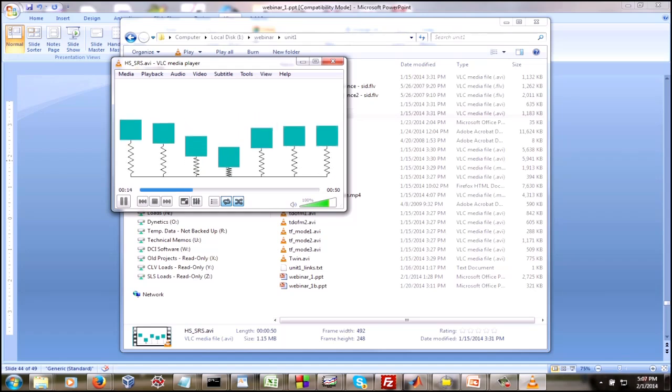Well, there's some other concerns we might have too, and if you deal with avionics components on launch vehicles, you'll come across things like C-band transponders and telemetry transponders or telemetry transmitters, and these tend to output a lot of heat energy, and that heat energy needs to be dissipated. So maybe that avionics component is mounted on a metallic bulkhead which serves as a heat sink, and it needs to be hard mounted for maximum heat transfer effects. So for those type of components, the thermal considerations in many cases would outweigh the vibration and shock type concerns.